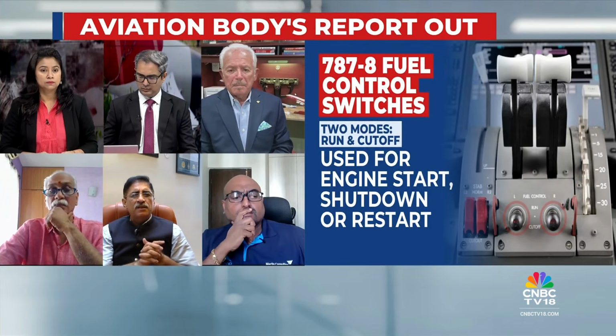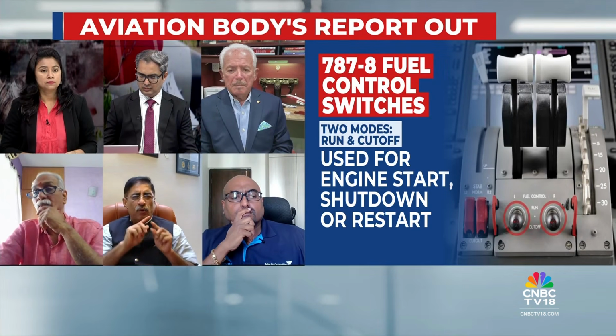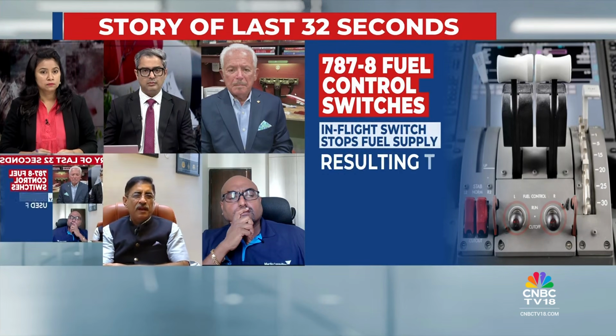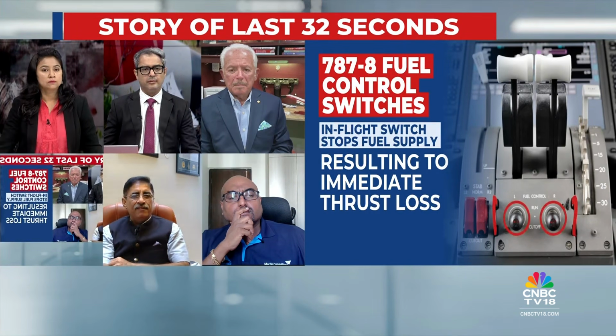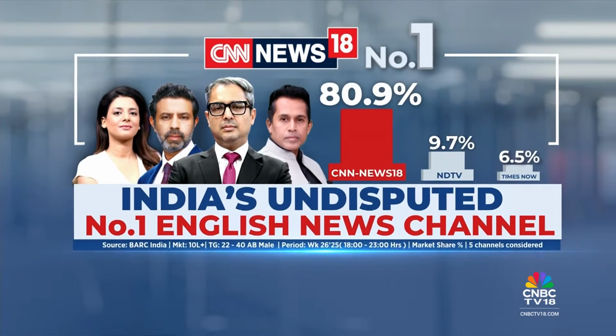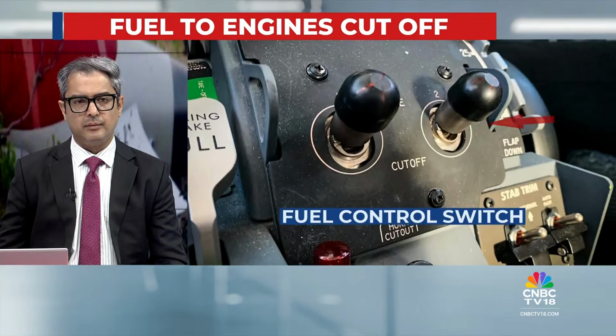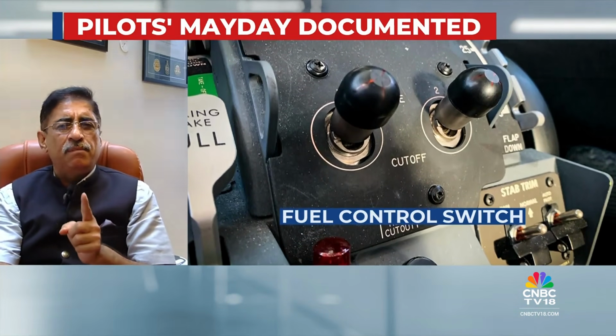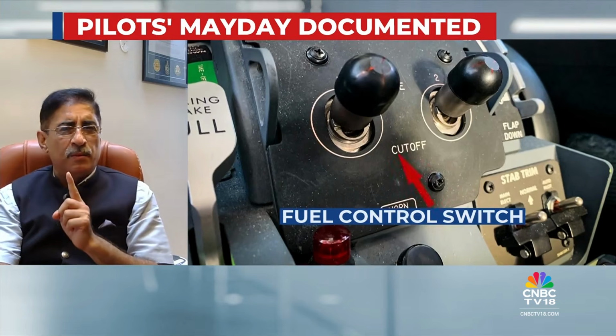The most important piece, Zaka, in my appreciation, that we are missing out is that the pilot has given a mayday call. Why would a pilot give a mayday call at unstick? It means he has experienced loss of thrust on both the engines. One engine itself is capable of taking this aircraft up and away.